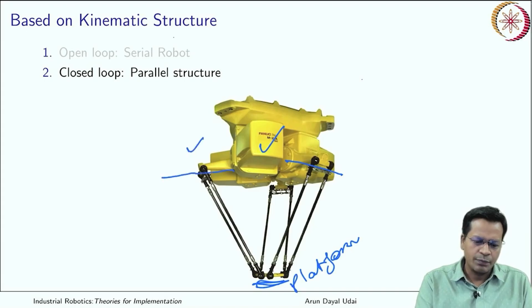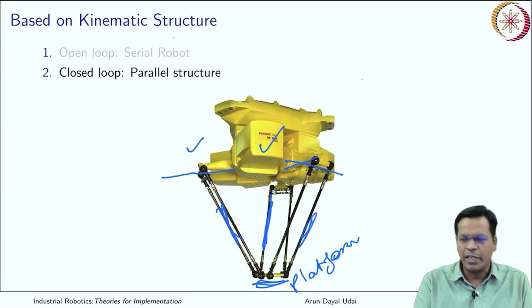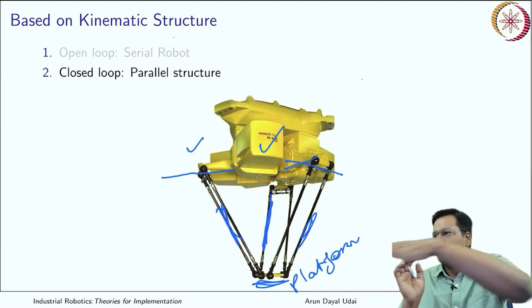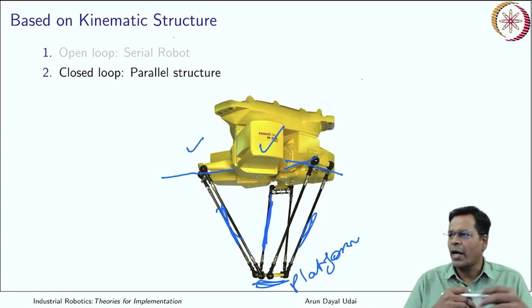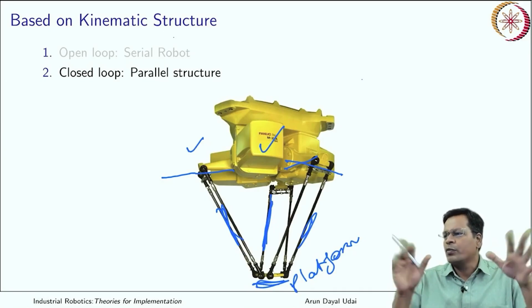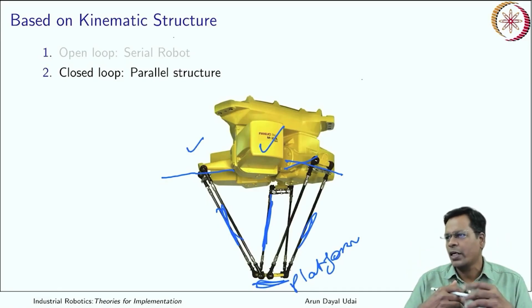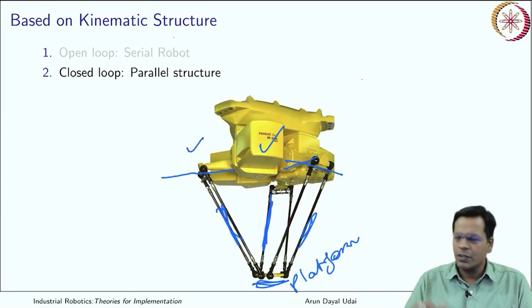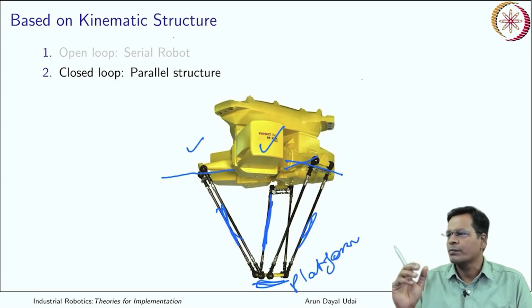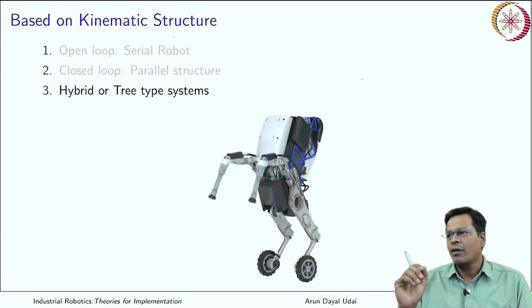So all the levers you can move, and this can go up and down, this can move, and that makes this platform go anywhere along X, Y or Z directions. Okay, so this is a parallel robot when all the 3 are moving simultaneously. I'll show this in operation while I'll be discussing serial and parallel robots in one of the lectures in this module.